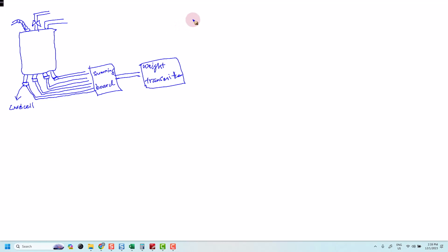So we have to understand the meaning of dead weight. Dead weight is just a fixed weight, or static weight. Basically, when you do not fill any product or water into the tank, the weight measured by the transmitter is called static weight, or basically just an empty tank or empty vessel.